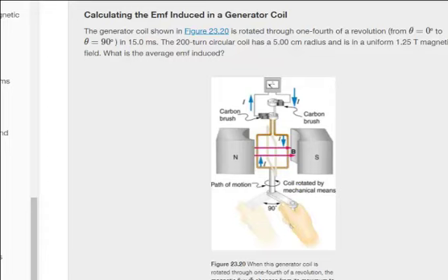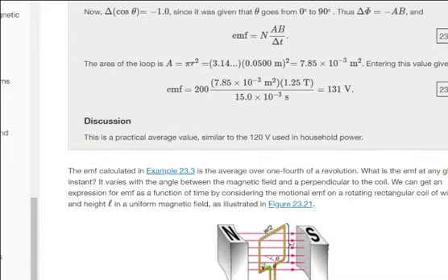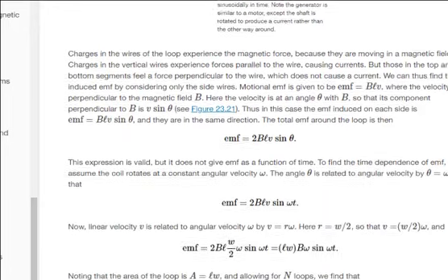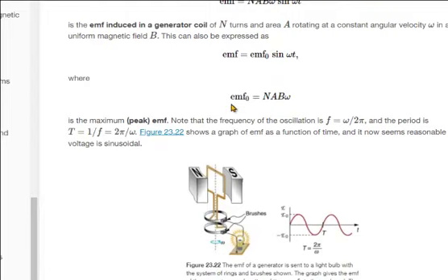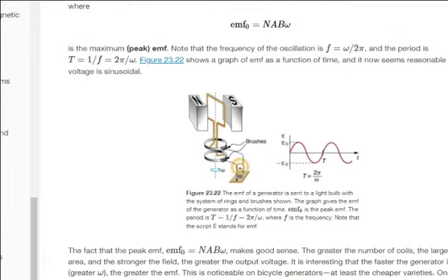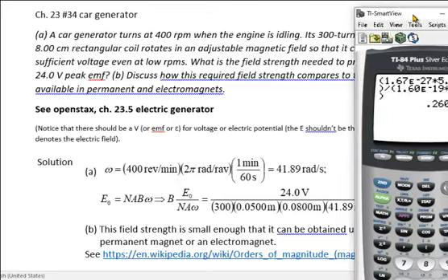All right, then you have these formulas here. Here's the magnetic flux, and because the angular velocity is given, 400 RPMs, you go through the motions of the algebra, and you end up with this equation, I believe. Let's check that in a moment. I think that's right. You end up with this one here, and then you solve it for the magnetic field. So let's go back. Yes, I was right about that. There we go. First of all, the RPMs are given as 400, so you have to get it into standard units, so per second, radians per second, respectively hertz.